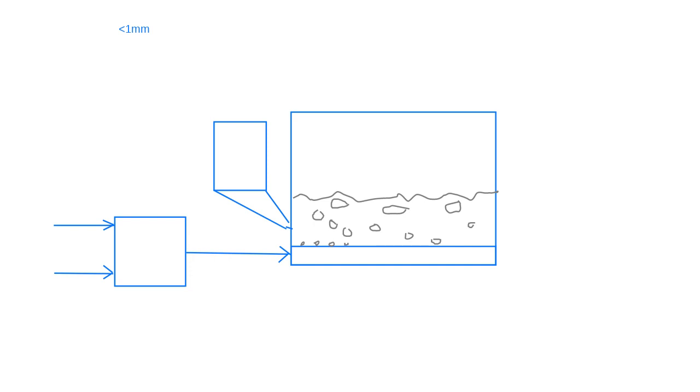So there again, you probably have a rotary valve operating to let a certain amount go in, or actually more often than a rotary valve, you would use an auger, a screw conveyor. That is a tube with an Archimedes screw in that tube, and that will propel the wet particles into this fluidized bed.